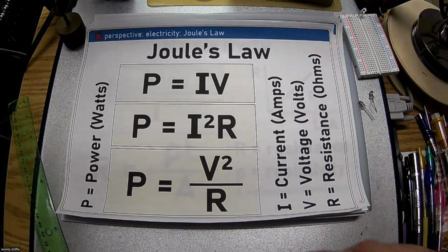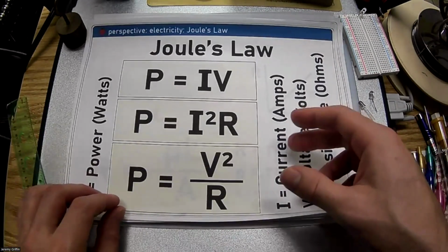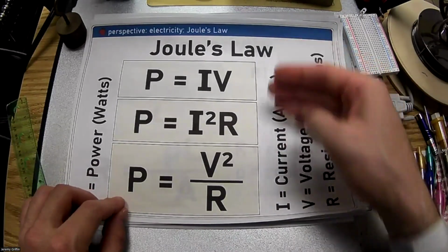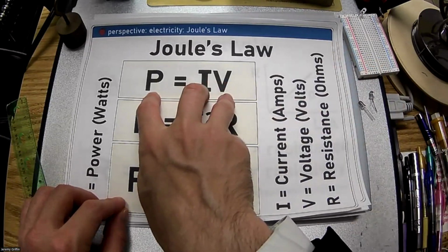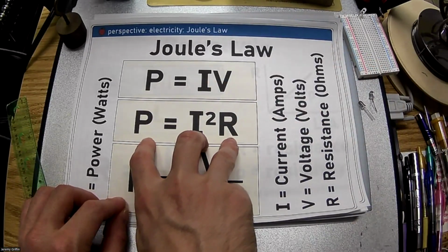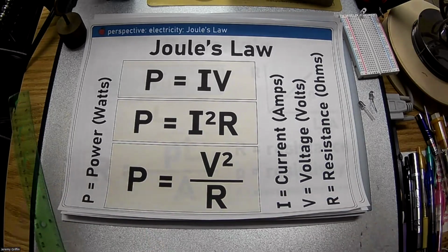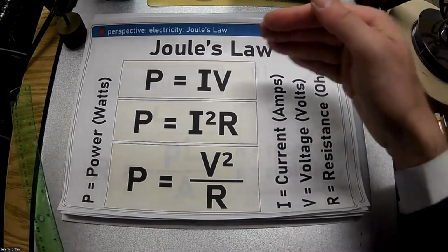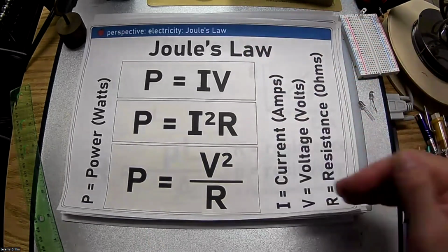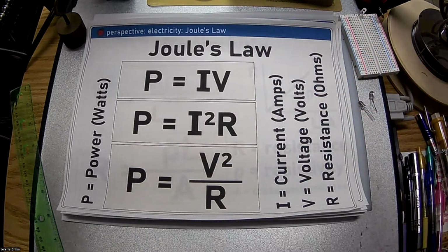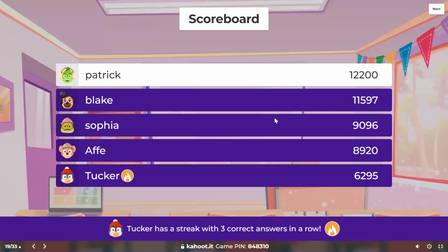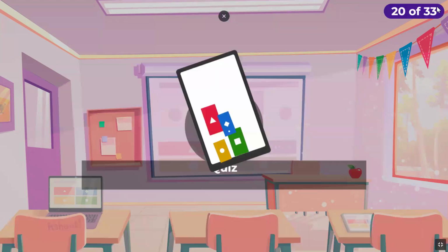After those, the next few questions will use any version of these. Power is current times voltage. Power is current squared times resistance. Power is voltage squared divided by resistance. You might remember from last week, completing all those Kirchhoff tables, that any one of these always leads you to the same power in watts. Some version might be the most convenient to answer a particular question, depending on the scenario you're given. All the same power in watts. All right, let's see how we're doing here.